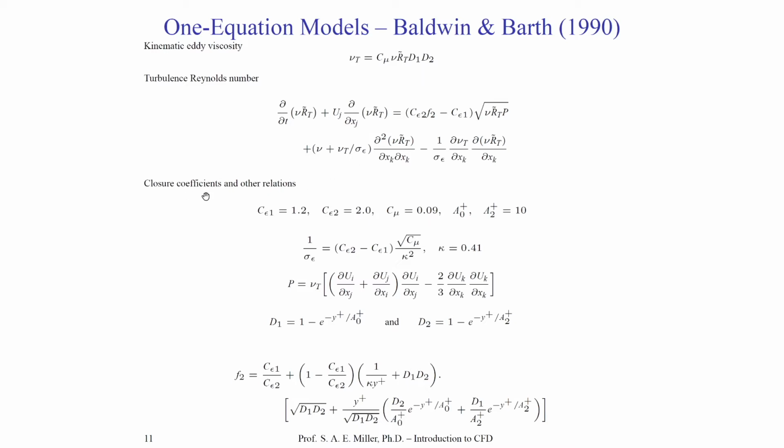You can see all the closure coefficients and relations of Baldwin-Barth's paper listed down here on the bottom of page 11. There's a lot. Some of them are actually forms of partial differential equations, which are closed, and some are just constant coefficients. But you see, this is one particular algebraic equation.